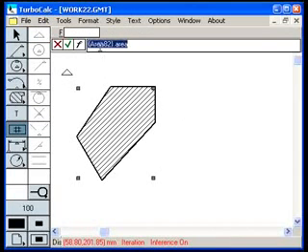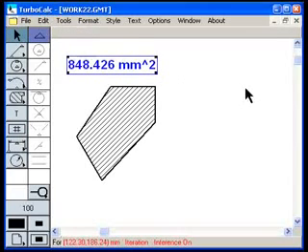The tag for the geometry, augmented by the area calculation built-in function, is automatically placed in TurboCalc's formula bar. There are 88 such built-in functions available in TurboCalc's formula bar that can communicate with geometry, dimensions, and empirical values in the worksheet to help you to automate a wide range of engineering calculations. So here is the area.